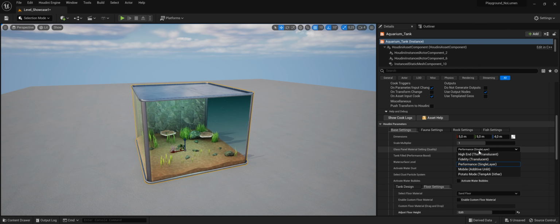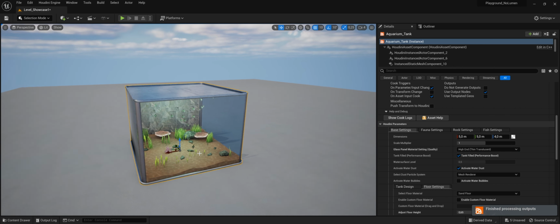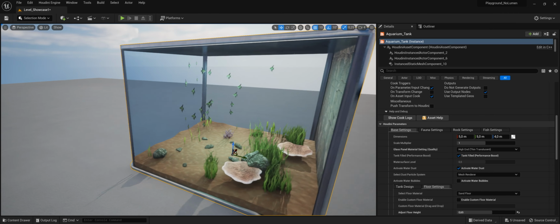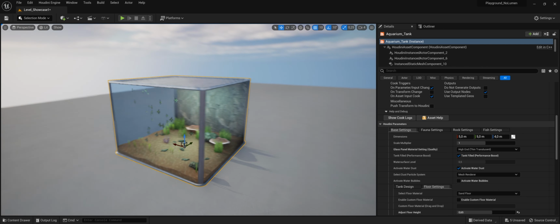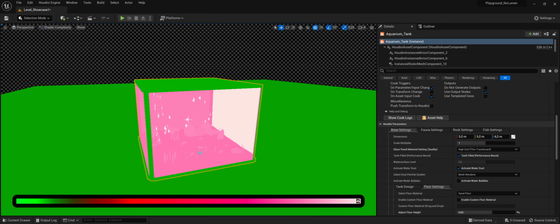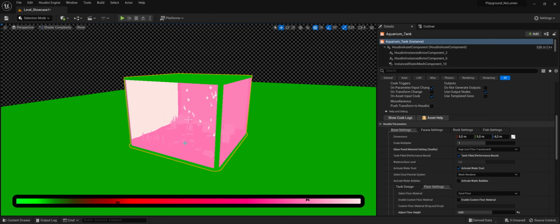Besides the single layer option, there are other choices available for the appearance of the aquarium glass, including a standard Unreal translucent material or an additive unlit glass material that optimizes rendering efficiency. For this showcase, let's opt for the latest and greatest shader model Unreal has to offer, the thin translucent material. With this shader I can accurately depict tinted and colored transparent glass, however it's the most resource intensive material to render. When switching to the shader complexity view in Unreal, you can see how expensive it is to render this material in conjunction with the water volume.